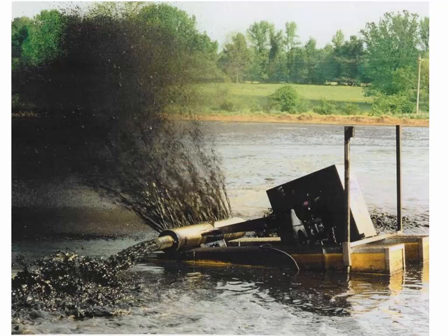Here's the simplest thing you can do with sludge. Just put it into a big lake, a lake of sludge, and aerate it. This is letting Mother Nature take its course, basically just having the bacteria that will start to grow in a sludge lagoon break the sludge down aerobically. The purpose of this device is just to recirculate the sludge into the air and try and provide some aeration. This is a surface aerator, similar to the surface aerators that we saw for secondary treatment pictures previously.